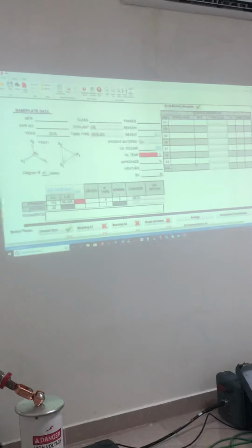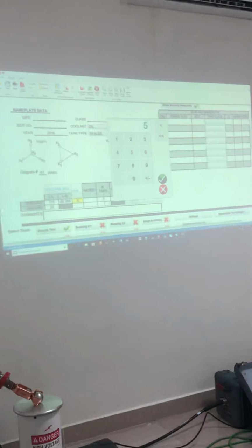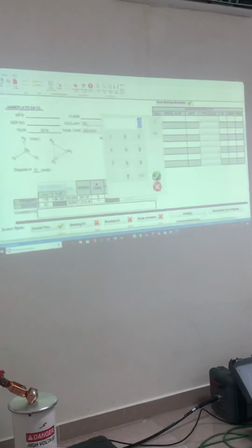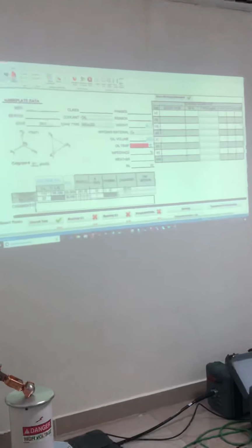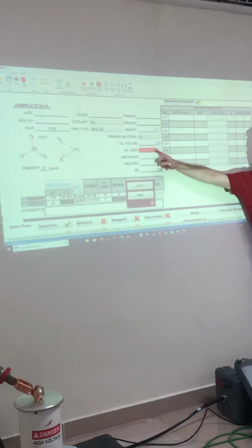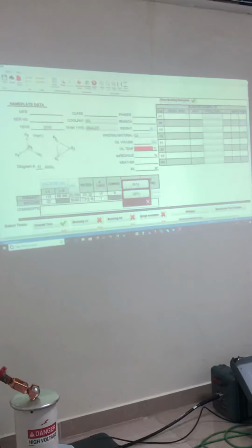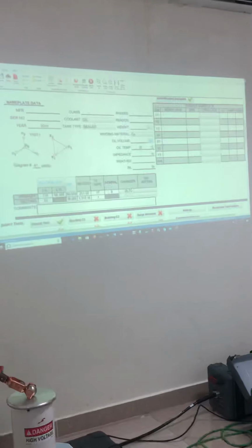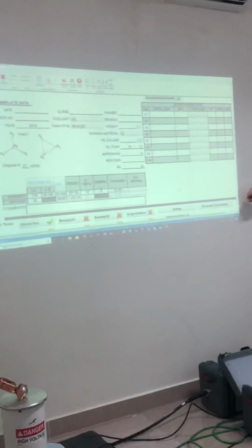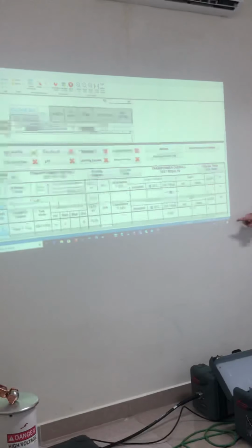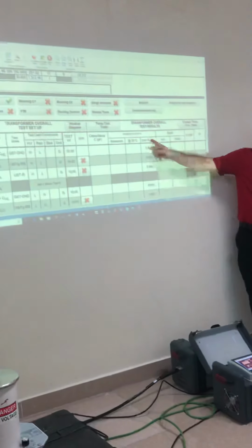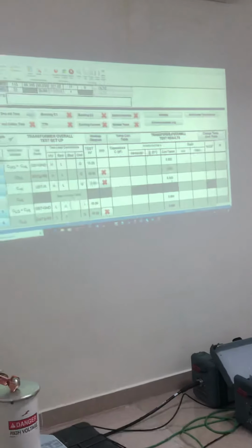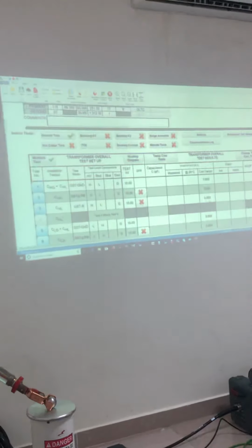So the question is, temperature correction, does it use ambient temperature? When you look at the tables, no, it just uses your oil temp. Just guess, say 30 degrees. So, there we go. Now if you scroll down in the table, you will see that now we have this correction factor that comes from the table that's based on the year of manufacture, the oil temp, the line-to-line voltage, and the kVA.